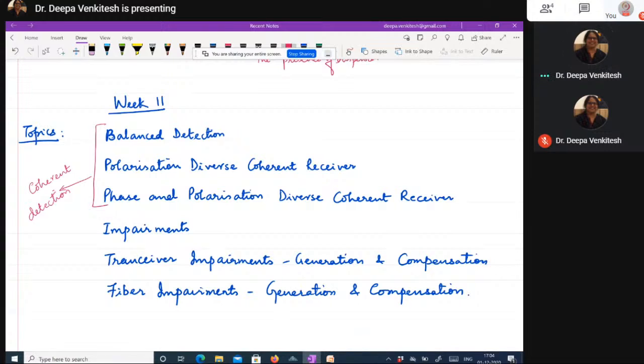So earlier, to improve the link budget, people had started using coherent detection, essentially with a heterodyne detector with a local oscillator, to push the detection into the shot noise dominated regime. But when we started modulating information in phase, this became more of a requirement. And so we saw the evolution of the different detection processes. First, we saw the case of a simple balanced detection.